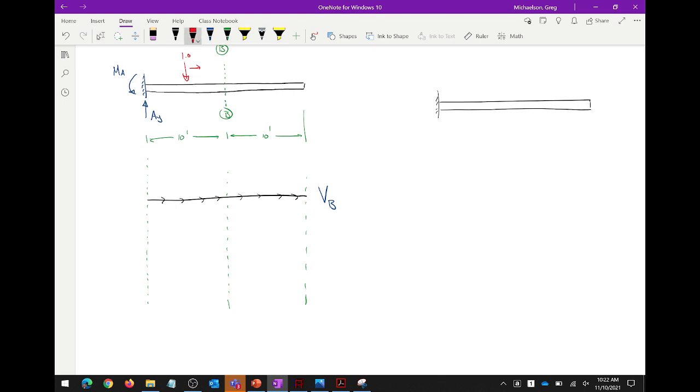And what we're doing for shear, now what did we do last time and what did you do on your homework assignment? We installed a shear release, right? And we trended the left side down and the right side up. Is that right? So does that mean that the influence line looks like this? Is that what that means?